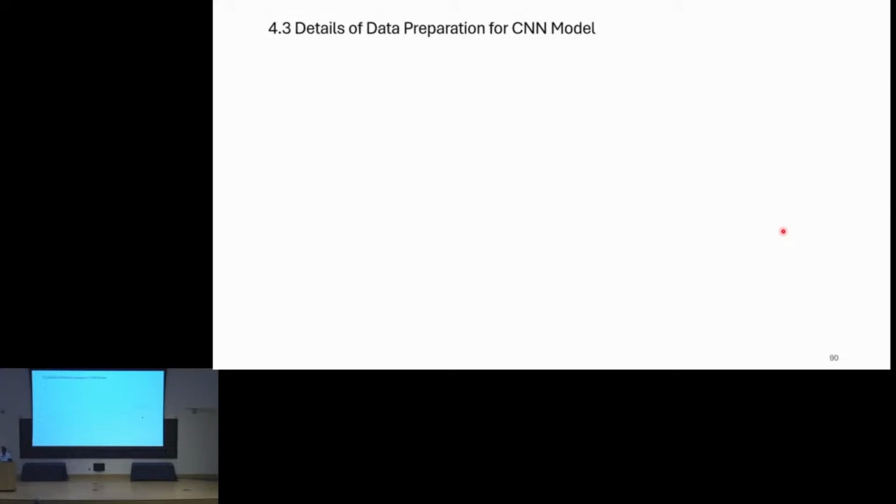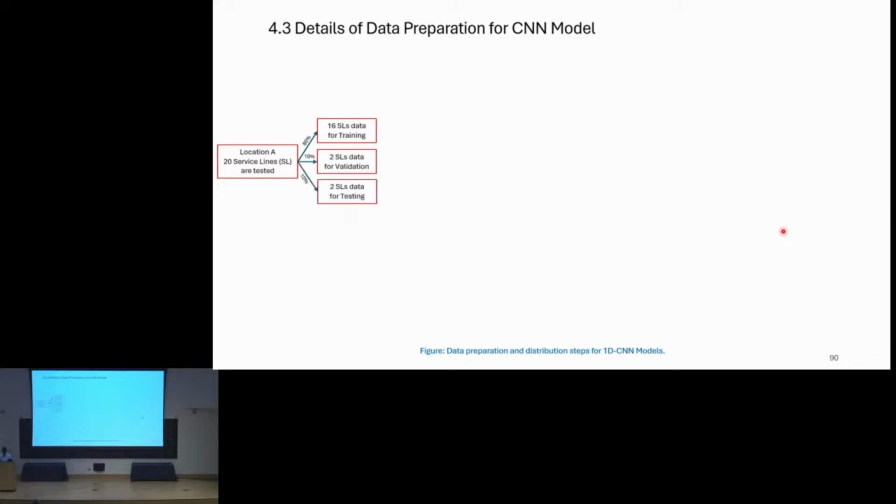So what we did is this. Let's say for a location, we have 20 service lines, and we used 80% of those service lines' data for training, 10% for validation, and 10% for testing. Among, let's say, 2 service lines from the validation data, let's consider only 1 service line. For 1 service line, as I mentioned earlier, we recorded 15 to 20 sets, in some cases 10 sets. So 10 hammer strikes with 3 sensors yield 30 raw signals.